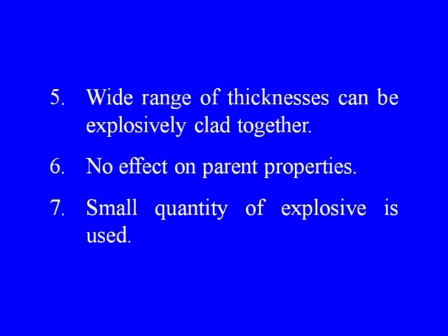No effect on parent properties can be observed, because there is hardly any thermal effect involved, and therefore the parent material properties remain intact. This is very significant, because we have already seen in a few other processes where heat affected zones are formed, the parent material properties get changed, which may not be desirable in many cases. And of course, the quantity of explosives required may not be very high.